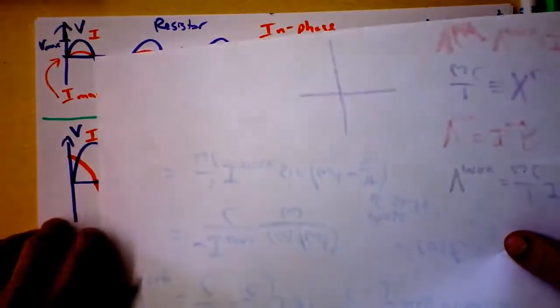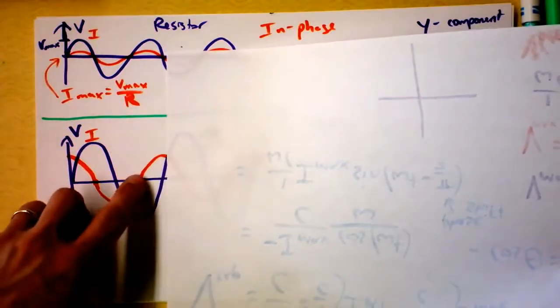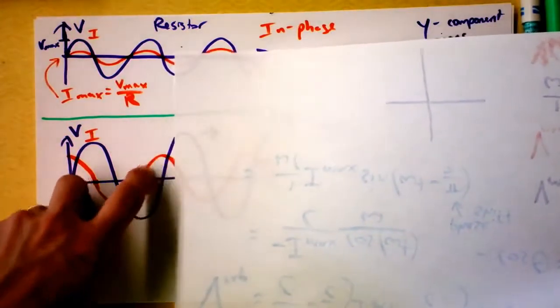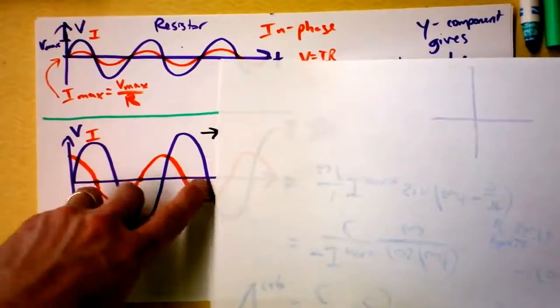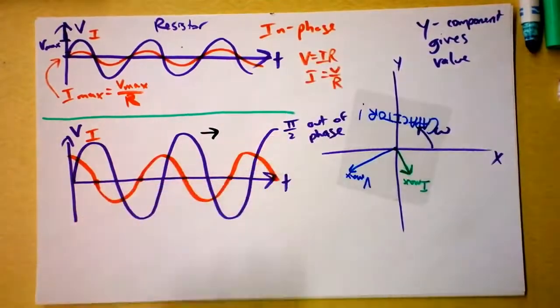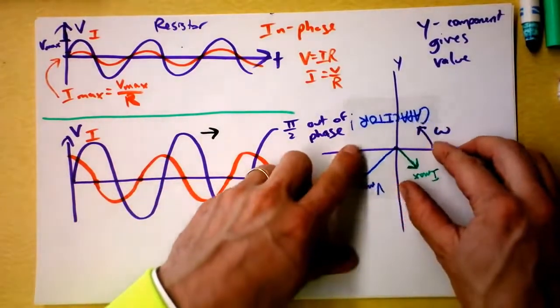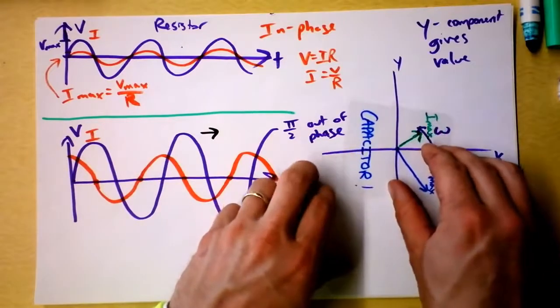So we're saying at this instant right here, we've got that, and then, oh man, see, that's going down, and now that's going up. Which one looks like it's leading now? It looks to me like the orange is leading, because the orange leaps up, and then the purple's like, okay, we can go up. And then the orange shoots down, and the purple's like, okay, we can go down. And then the orange shoots up, and the purple says, okay, we can go up. All right, so that's why it's consistent to say that the voltage lags the current for a capacitor.